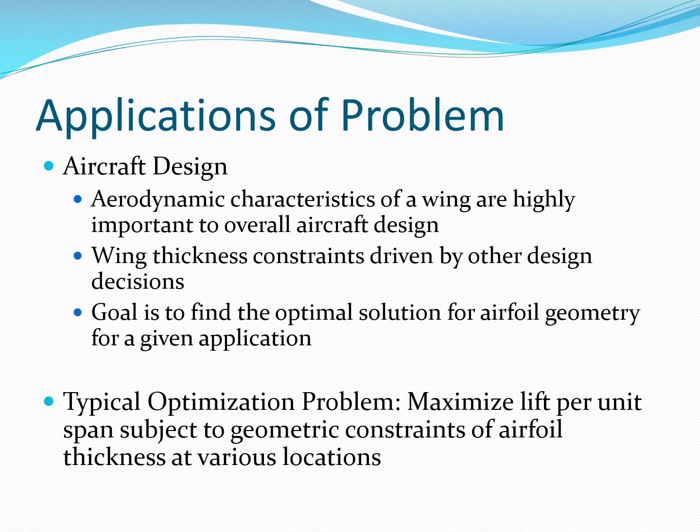Lift optimization is important for overall aircraft design, especially when thickness constraints may be driven by other design decisions, such as equipment installation or other structural considerations. The goal is always to find the optimal airfoil design for a given application. This leads to a typical problem of maximizing an objective function subject to various geometric constraints.